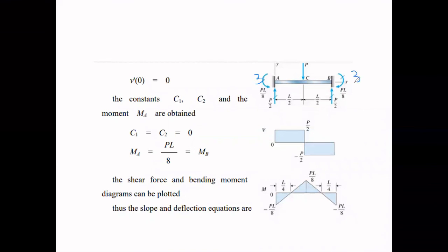Three support reactions are over here. So the basic indeterminacy in this case is three. We can clearly see at this end, the number of reactions is three, and also at this end, the number of reactions is three. So we just need to calculate it like this. The total number of reactions is six, and 6 minus the equilibrium conditions, and the equilibrium condition for a 2D frame is 3. So the total indeterminacy in this case is 3. So basically we can clearly see that three extra equations are there. Hence we need to calculate the unknowns, and in this case the unknowns are HA, HB, and also MA and MB.